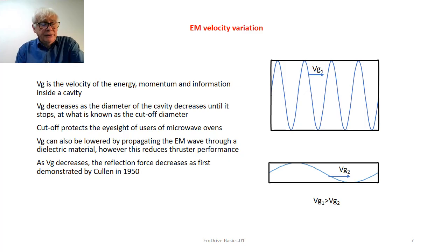Interestingly, the guide velocity can also be decreased by propagating the wave through a dielectric material inside the cavity. If you fill up that circular cavity with a cylinder of dielectric material, then again the guide velocity will slow down.